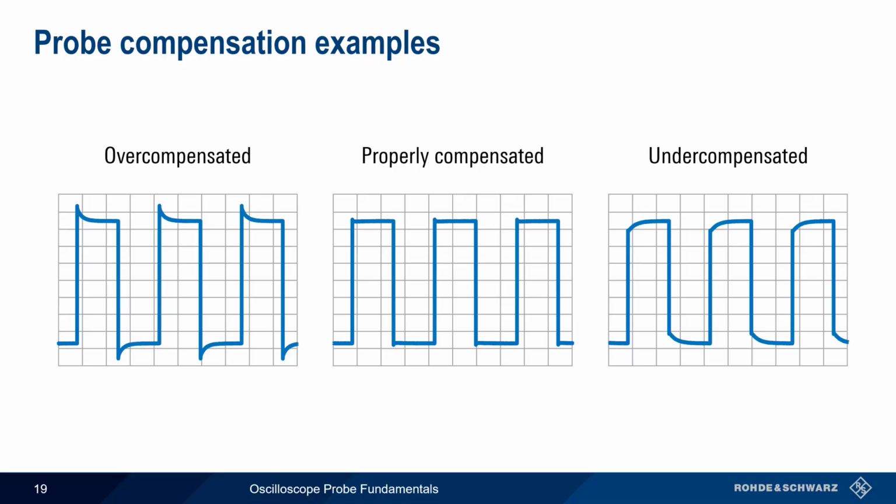As mentioned a moment ago, probe compensation is nothing more than adjusting the compensation capacitor until the displayed compensation waveform has rectangular edges. Note that this usually takes only a small fraction of a turn.